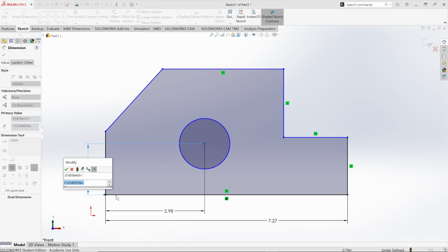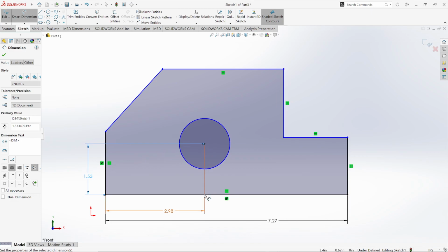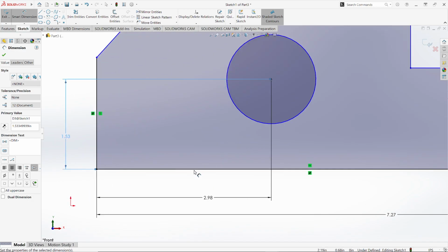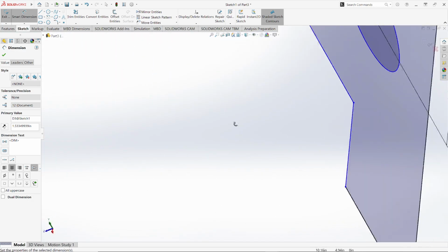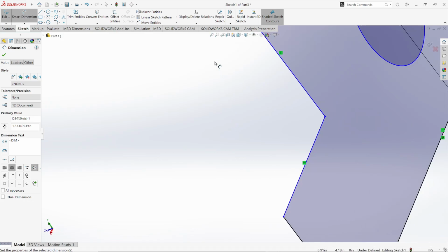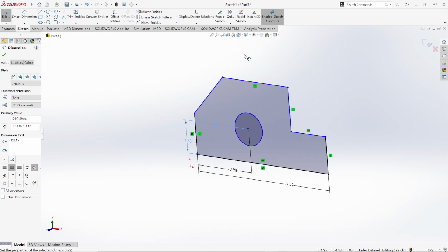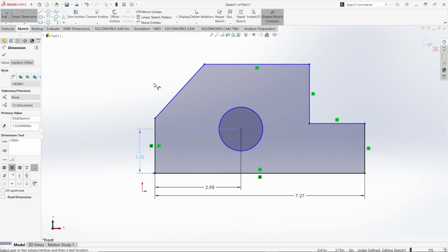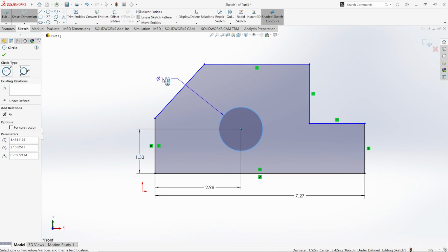The shop now knows that they're going to measure from the left edge over to here, from the bottom over to here, strike a point, and that's where they're going to dimension to. It almost looks like it's, shoot, almost looks like it's off there. All right, I'm going to trust it's not, and I'm going to put on one more dimension by selecting the edge of the hole, and it should give me the diameter callout.